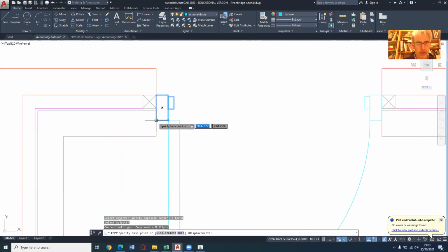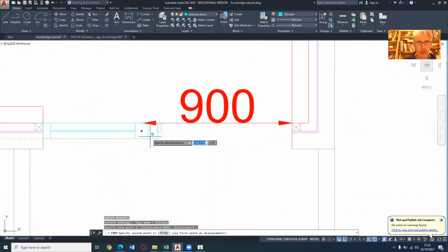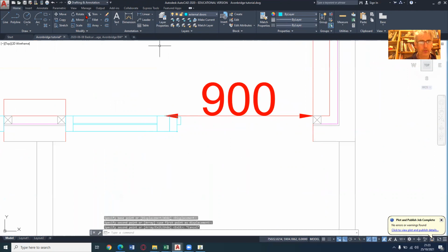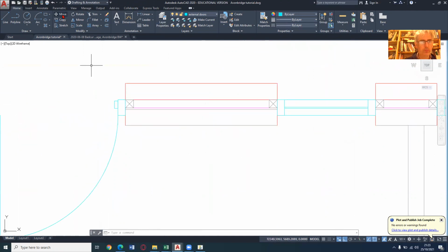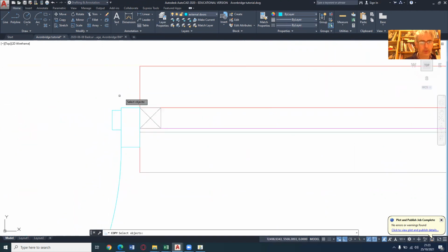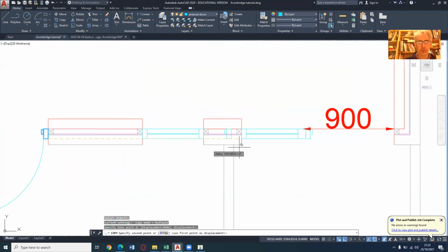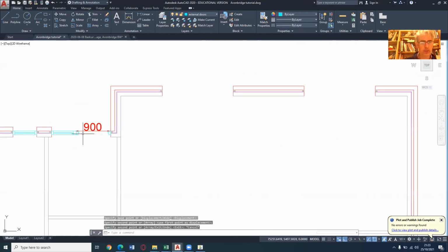And again, I'm using my control point. I'm going to just drag that across in a copy fashion to here, and we're going to mirror that to the other side using our mirror command. Okay, in fact, we'll change my mind. What we'll do is we'll just copy this one here, and we can copy that across. So there's a couple of options open to us. We could have flipped it over, or what we could just do is to use a copy command.